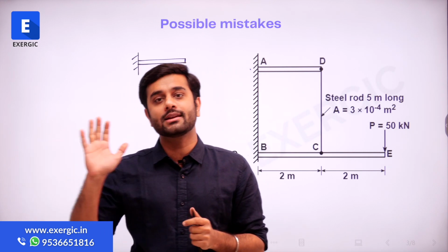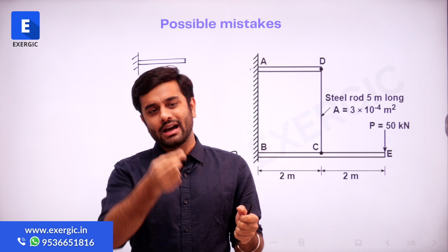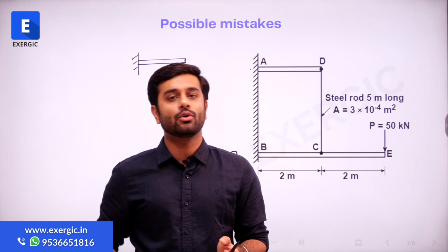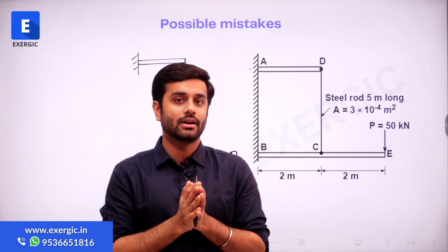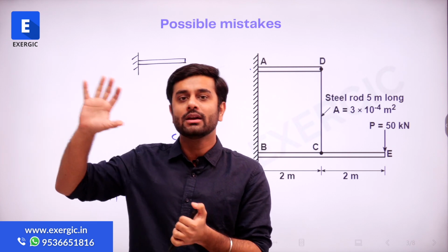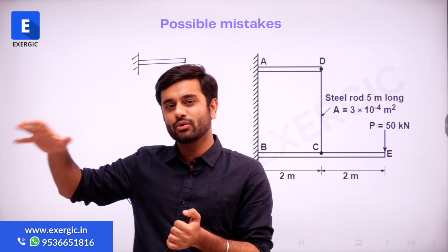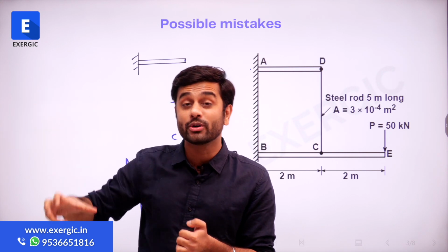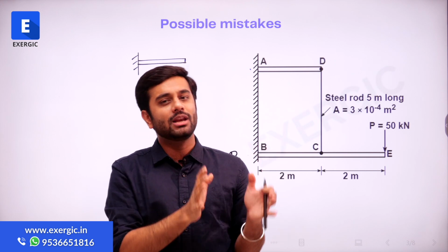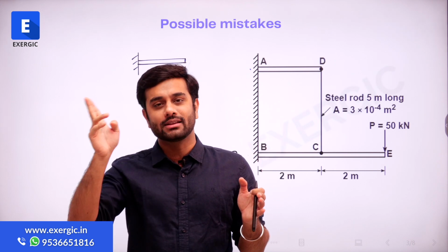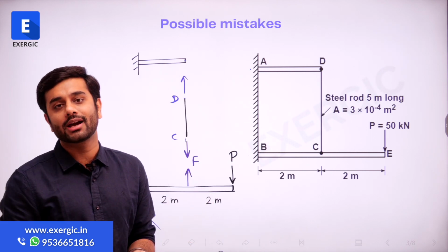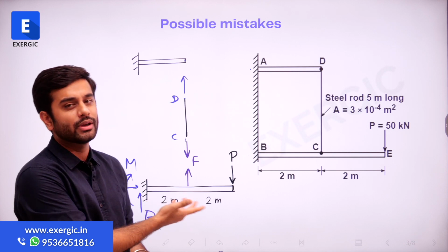So whenever you get a question where you can see that there are some additional connections, maybe in the form of a rod, maybe in the form of some load, look at the question and figure out what the different connections are. We have discussed connections in strength of materials, also briefly when I was telling you about loads, and in mechanics also we have covered different types of connections. That will give you a hint that maybe it's statically indeterminate, and you can quickly check it by making the free body diagram, like we have checked it here.